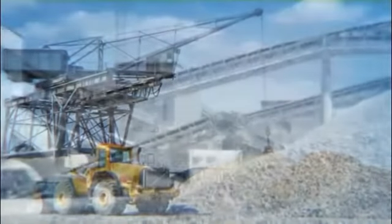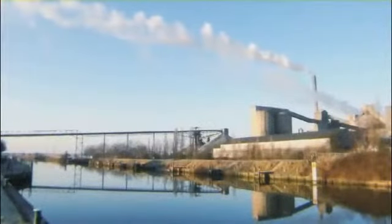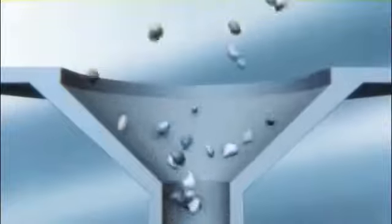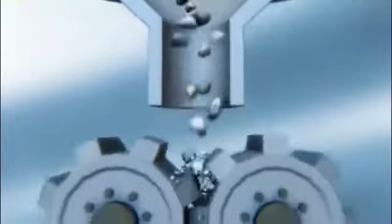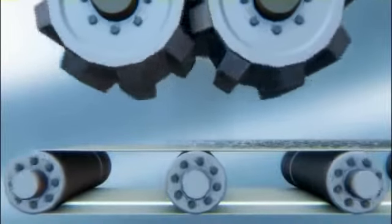The feedstocks used for the manufacture of cement are the natural raw materials limestone and clay. These are broken down in crushers into fragments of about 1 kilogram and then ground in a raw mill, together with smaller amounts of iron ore and quartz sand to obtain a fine meal. At the same time, they are dried with the hot kiln exhaust gases from the incineration process.